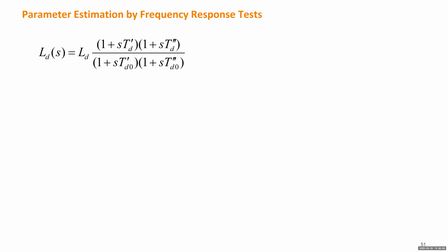But there could be two concerns. The first one is that when they do such testing, they put it in their test bed. That doesn't represent how the generator behaves in a real power system. Actually, the same problem is also true for IBRs and a lot of renewable generators, such as solar farms or wind farms. The model they give you is only accurate for very small systems. They set up a very small environment to test the parameters, but when you connect to a large grid, some parameters need to be identified again. You have to do what we call model validation. So even if they gave you those initial values for those time constants, you still may want to do your own test to verify or validate those parameters.